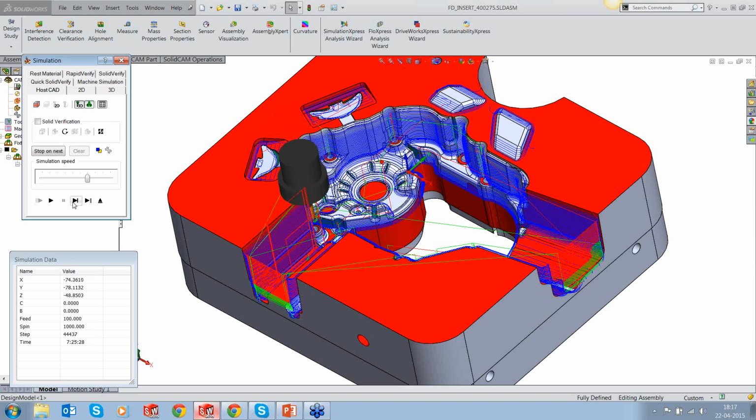That means in case there is no collision between the holder and the part geometry, or the part geometry is quite away from the holder, it will not tilt to 5-axis, but it will be 3-axis itself. You can see that as it goes into that region out there, where I'm marking right now, moving my cursor, that area out there is where you're going to have the proper tilt.